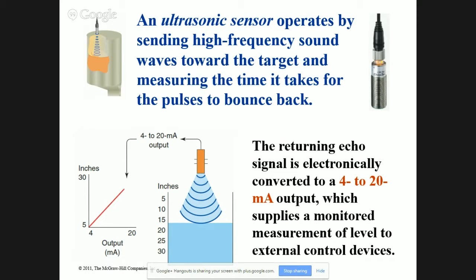Ultrasonic sensors, we hooked that up. It's an analog. Remember when we hooked up the ultrasonic sensor, 4 to 20 milliamp signal, and we put our hand in front of it, the signal went up and down. We have those on our PID trainers. Hopefully we'll get time, we'll get on those and you'll see it work.